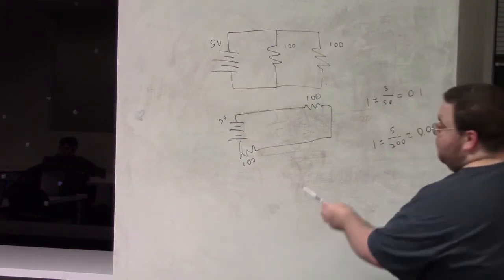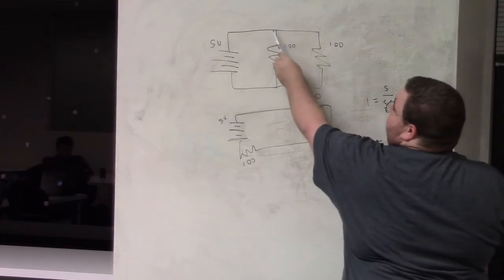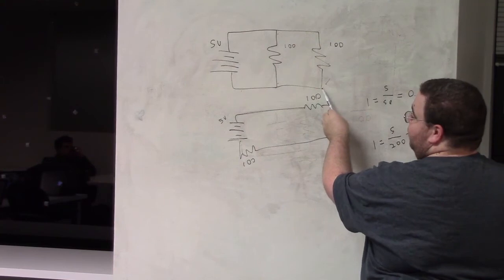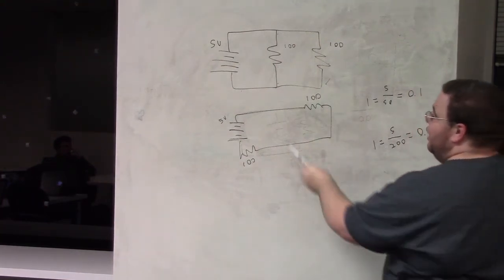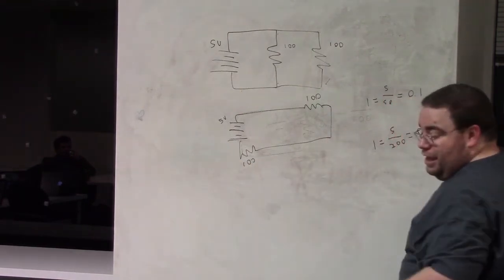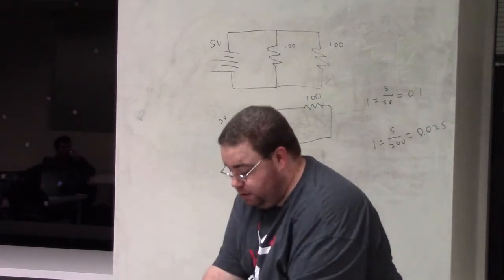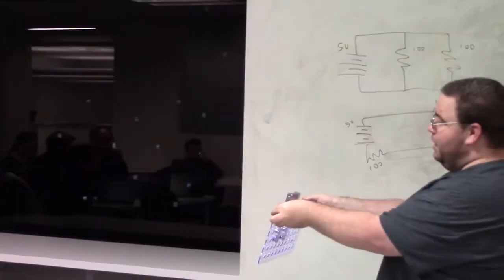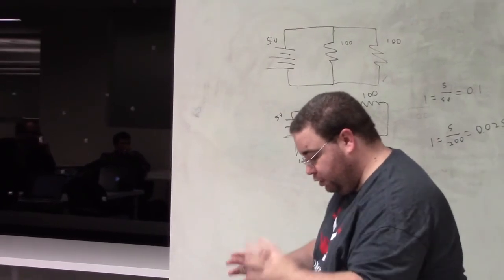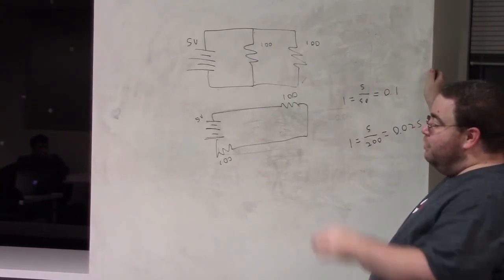Furthermore, a lot of that voltage is going to be eaten up by this first one. Everyone's getting an equal amount of current, but this guy is dropping from 5 to 2.5, this guy's dropping from 2.5 to 0. It turns out that if you look at this, one is now brighter than the other one. See? And you can see the same thing. It's actually worse with LEDs. But that's why you do things in parallel instead of in series, is to increase the amount of current going to each thing.